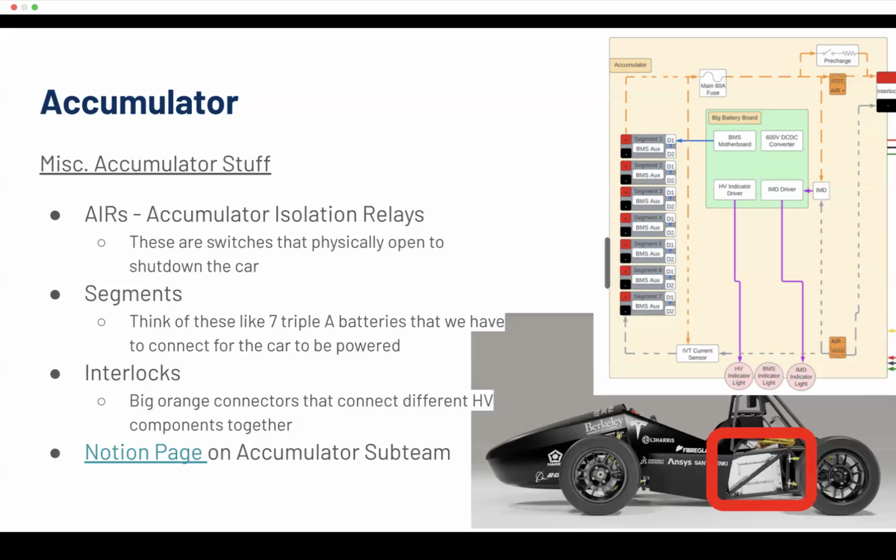So you can imagine before they're connected, it's like you're plugging in the battery for the first time. We have a circuit on the high voltage box side called the discharge circuit that, when the battery is disconnected, shorts HV plus and HV minus through a resistor to discharge a capacitor on the high voltage rail